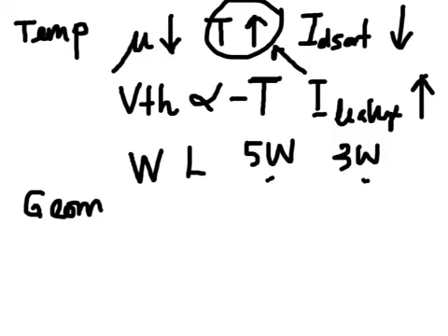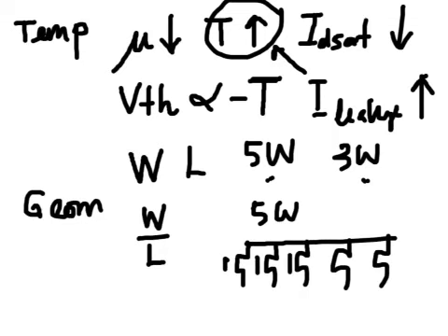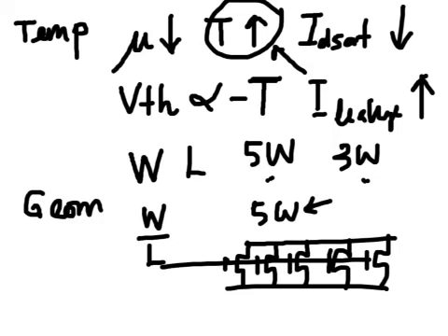And so what is frequently done is transistors are constructed to some unit ratio of width to length, and if a 5W transistor is required, what we end up doing is connecting in parallel 5 of these unit transistors as such. And this way we get a dependable and robust ratio and a robust way to scale width, length, and various parameters in the transistor.